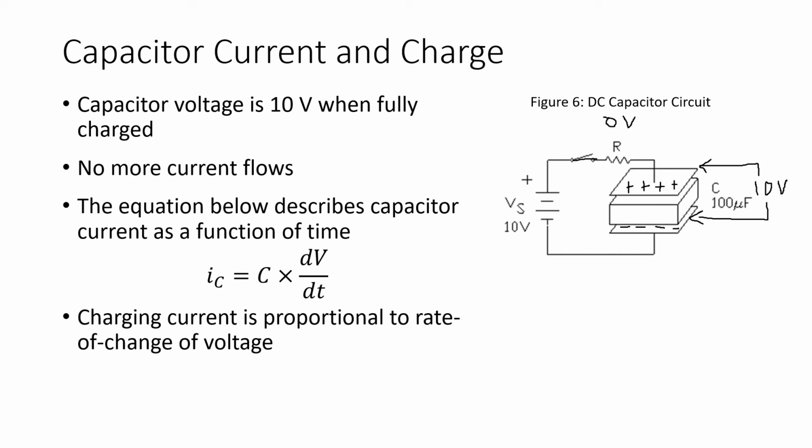Again, Kirchhoff's voltage law tells us that around this closed loop, the sum of the potential differences must be 0. So after the capacitor is fully charged, the current that flows in the circuit, I, equals 0 volts divided by some value of resistance. So we know that after the capacitor is fully charged, the current in the circuit equals 0 amps.